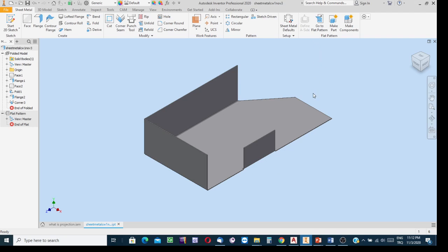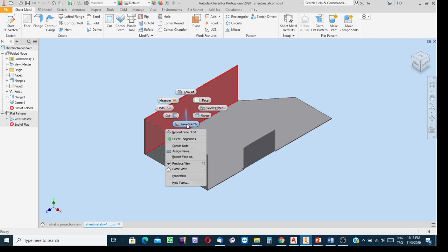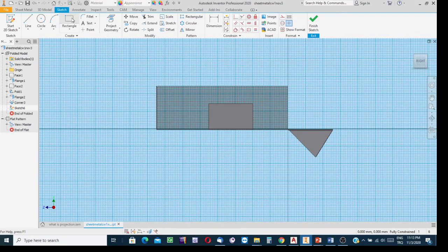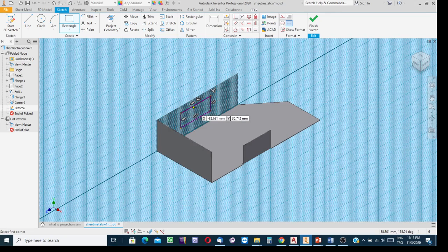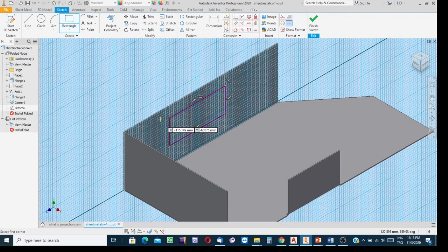Continue. Now here, say that over there we need to have a cutting rectangular in shape. Okay, click on this part, say that we need to have an empty space. Select this surface from this side or the opposite surface, not so important. And then create a sketch, rectangular in shape in this example, over this sketch plane. Since it is coinciding with the surface of the flange, it is going to be considered as if scribed over the surface of this sheet metal, and then the rest is the punching process, cutting process. Using a punch press and a certain special die, cut the material.